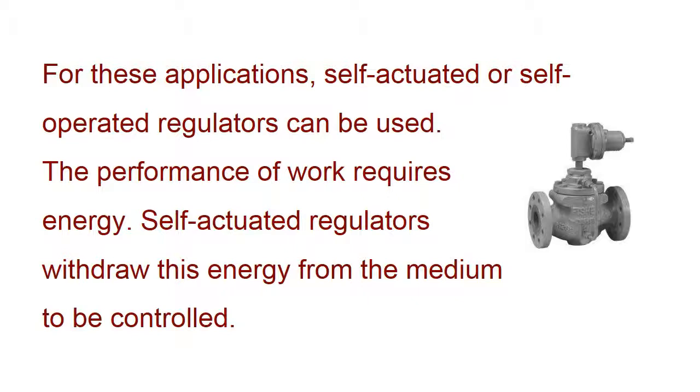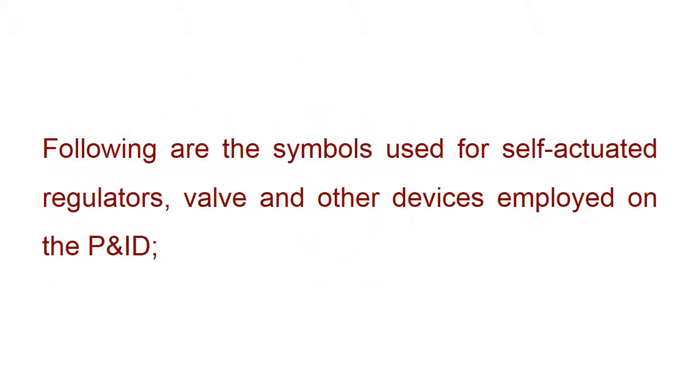The performance of work requires energy. Self-actuated regulators withdraw this energy from the medium to be controlled. Following are the symbols used for self-actuated regulators, valves, and other devices employed on the P&ID.